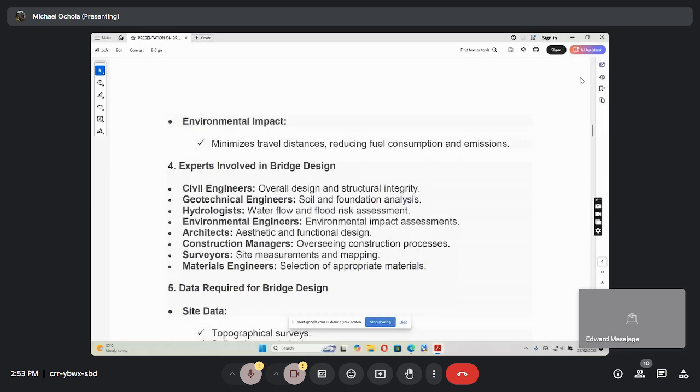So if it is being curved at that super elevation is what you design. And you must, because if you give a different shape, then that will become a black spot and become a safety issue. So in your design you also have to think about that. That is why civil engineers are very important. You look at the overall design and structural integrity.